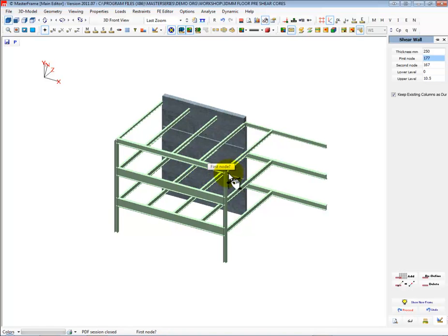It is in essence a single, as I say, column of the width and thickness that you expect, but we also then have these horizontal members at each level, which allow us to rigidly take our load from this point back to the center of the shear core. So these members here, these what we call rigid link members, provide a very useful tool and give us a correct analytical model. So a discrete shear wall, dead easy.